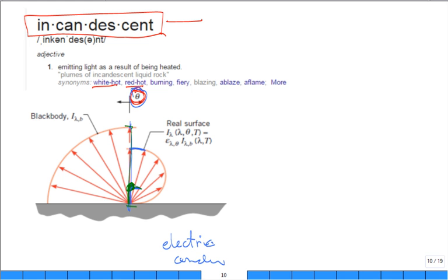Okay, so if it wasn't a function of the polar angle, it would just stay at that radius. But if you have an electrical conducting material, sometimes when it comes out like this, what's happening to the emissivity at shallow angles? It's getting larger. So if you have a metal sphere and you heat it up so it's just high enough temperature that it actually glows.